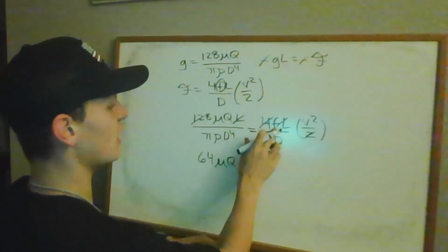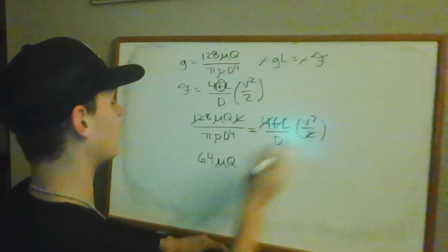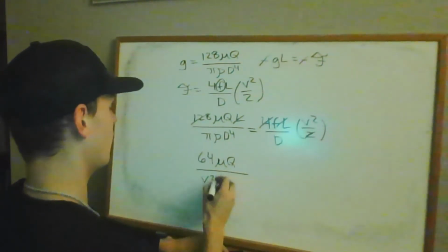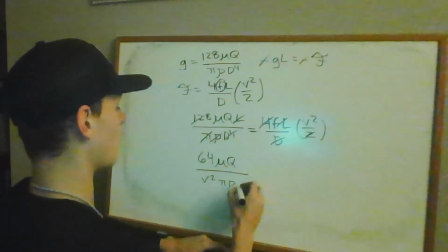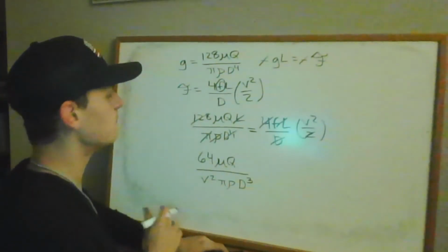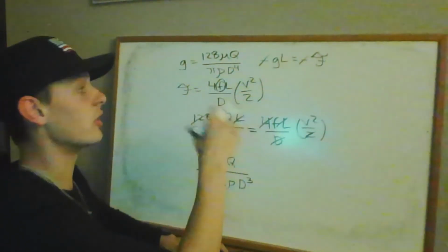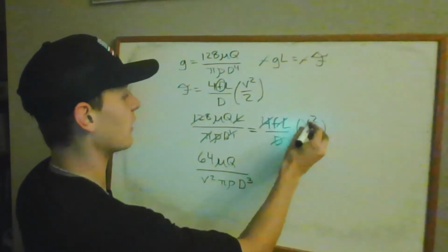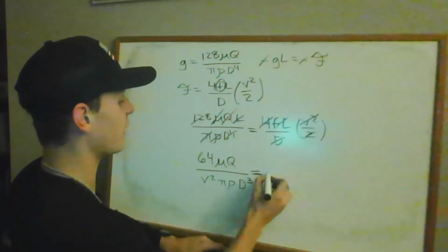Obviously, we're trying to isolate F, which is our Fanning friction factor. And then we have the v squared. Again, that's going to be part of this denominator here. The pi stays, the rho stays, so we've used those, and these cancel as well, so that we have the diameter of our pipe cubed. Notice that this expression had the diameter. That's why we made that change with the volumetric flow rate equation, in which we re-expressed it in terms of the diameter d. So we used the velocity squared, we used mu, we used q, and this is equal to the Fanning friction factor.